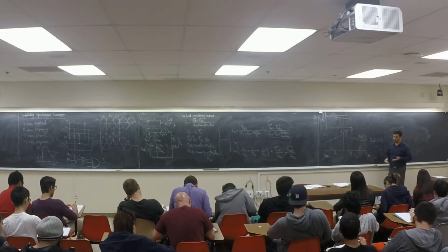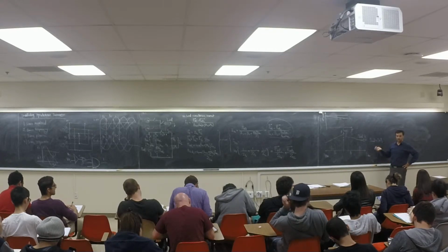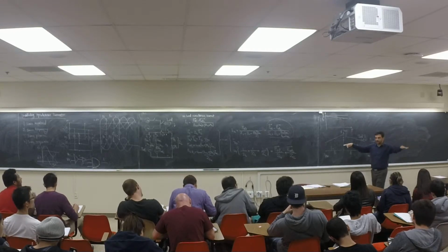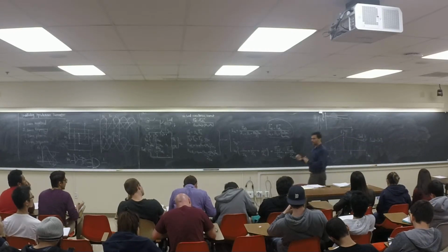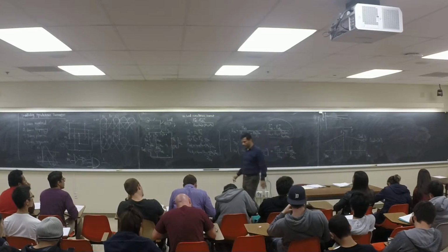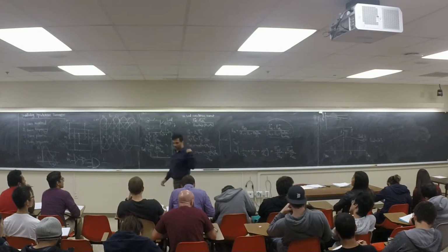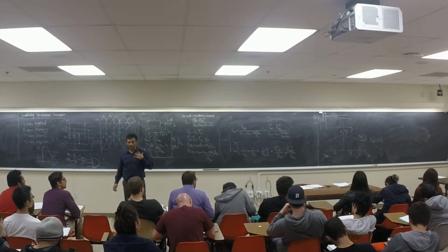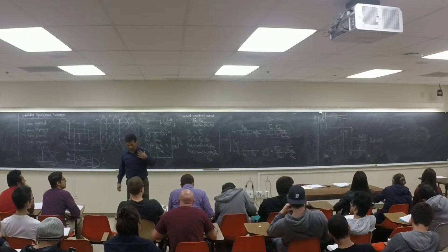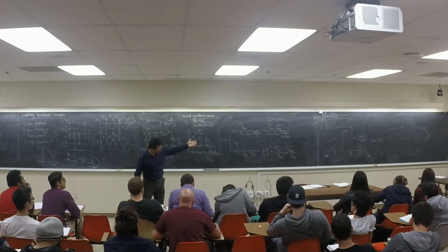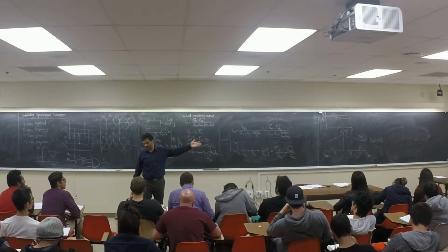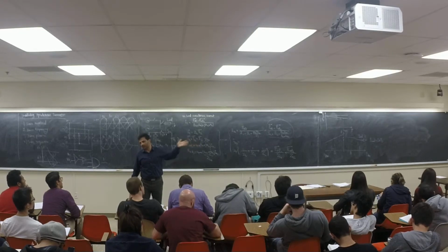Basically, I increased the load. Which one is going to give you more power? If they're two exactly identical machines, they're going to share, for example, with 10 kilowatts, 5 and 5, right? If they are not identical, like the ones I have on the board, which one is going to give you more power? Which one is the better one? For example, in this case, I think the one on the right side is the better one, right? So that one is going to give you more.